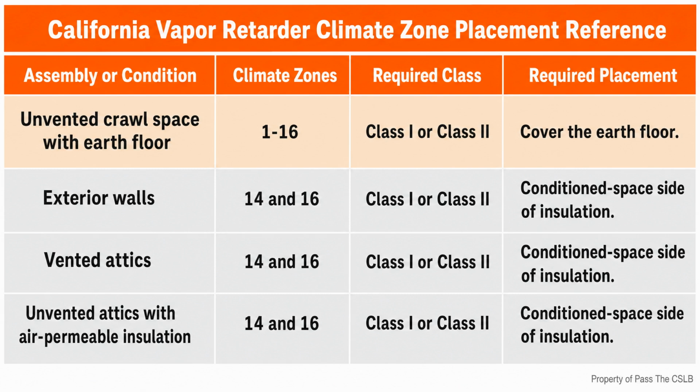Foam plastic can be part of a high-performance envelope, but it also brings fire performance limits. The California Building Code generally limits the flame spread index of foam plastic insulation and foam plastic cores to no more than 75, and the smoke developed index to no more than 450, based on the reference test method. Those index limits do not replace the requirements shown in the approved assembly and product information. They are a screening fact, not permission to improvise an installation.